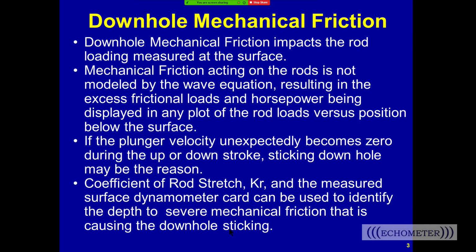What we see often is we see the plunger velocity, when downhole sticking becomes a problem, go to zero, and that can happen during the upstroke or the downstroke. And we're going to talk about this idea of the relationship between plunger velocity or velocity downhole with respect to a sticking force, and that's something that we'll see several examples of.